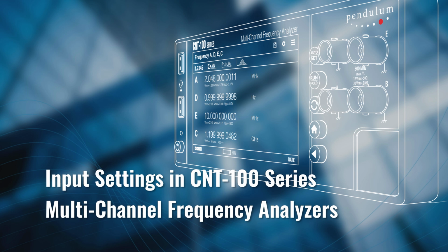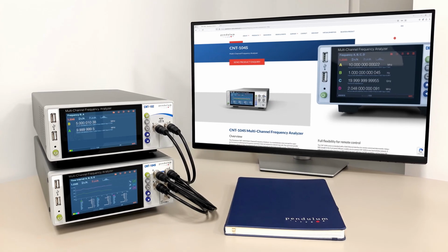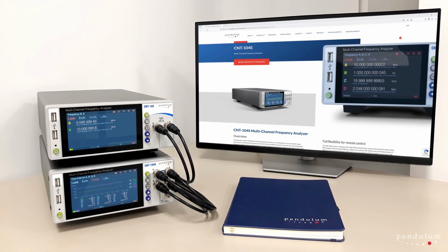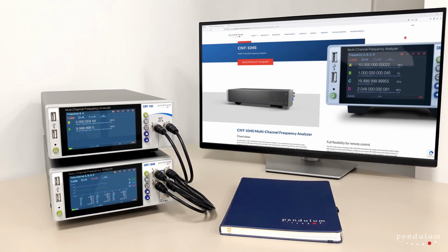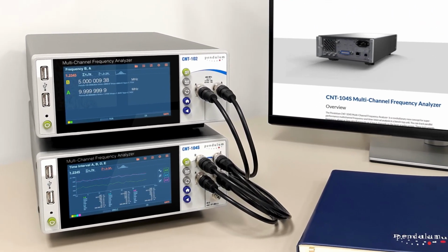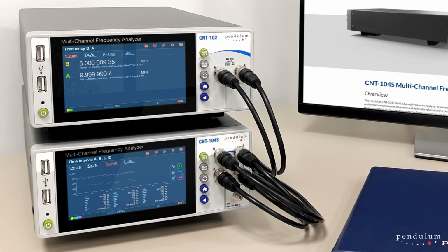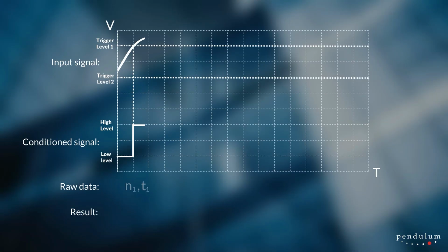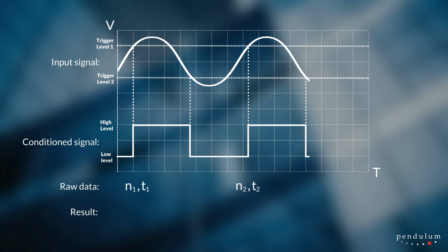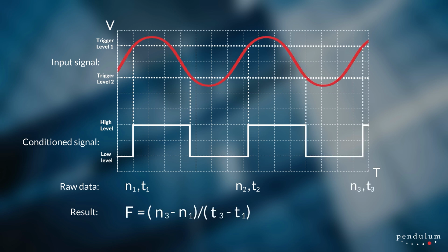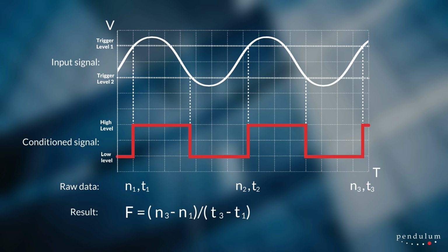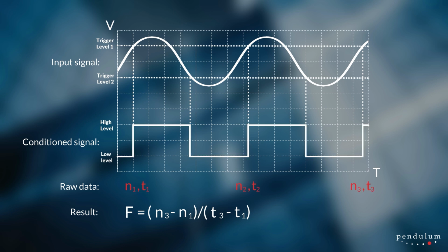The CNT-104S and CNT-102 are highly versatile multi-channel frequency analyzers, which are suitable for a wide range of frequency and time-related measurements. Whether you are measuring simple parameters like average frequency or more complex parameters like time intervals between several inputs, the operation of the frequency analyzer is always based on transforming the input signal into a pulse sequence in which transitions between two levels are precisely time-stamped and counted.